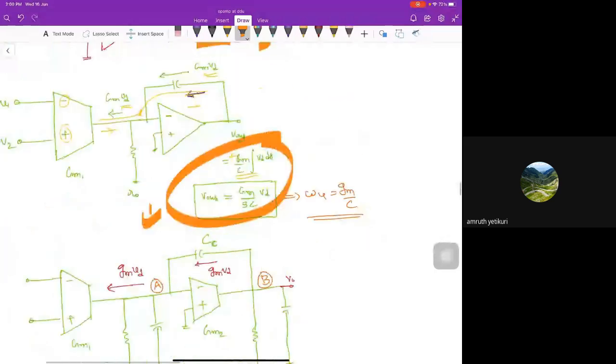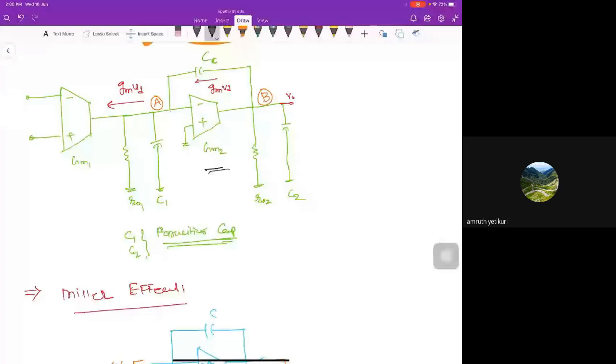So again, this is the op-amp here. I am using an op-amp to build the op-amp here. Is this the proper way? No. So again, take this into the OTA, meaning operational transconductance amplifier. We can build the OTA, so we have built it here. Again, I have put gm2 here with another OTA, taking the feedback through this capacitor. I am using this gm times Vd current and passing it to this capacitor and getting this output.